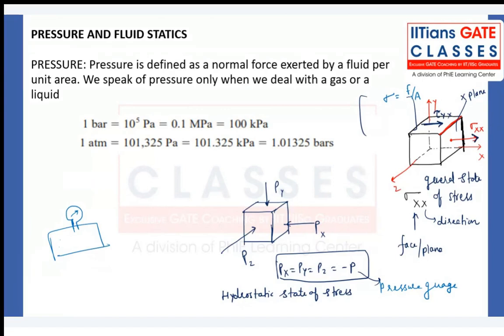Now, the magnitude of the pressure value at a particular point will be the same in all directions. That is valid when the fluid is under rest condition, but that is also valid when the fluid is under what? In rigid body motion, right? Now, what is a rigid body motion? We will see that. That is a different phenomenon.